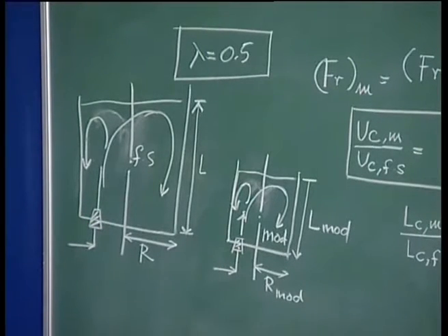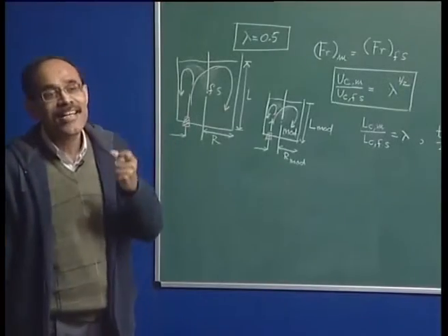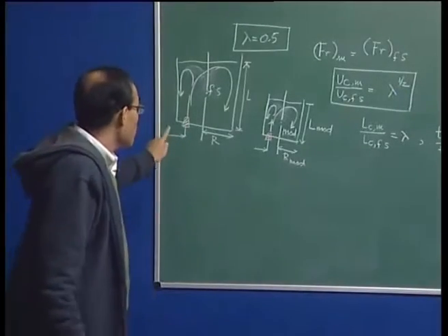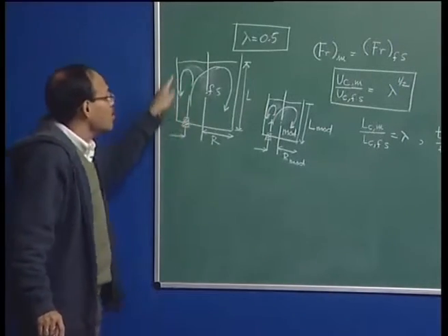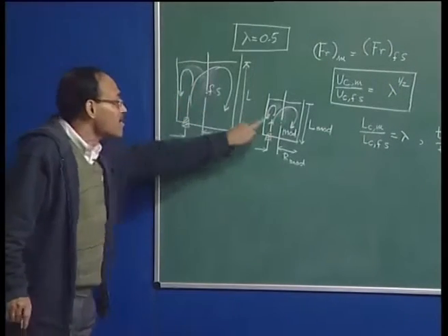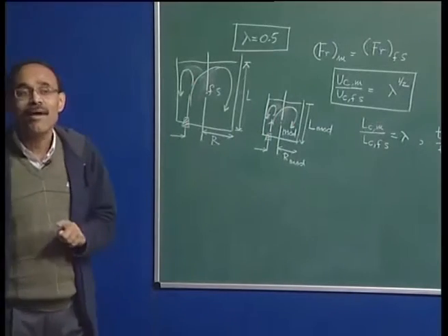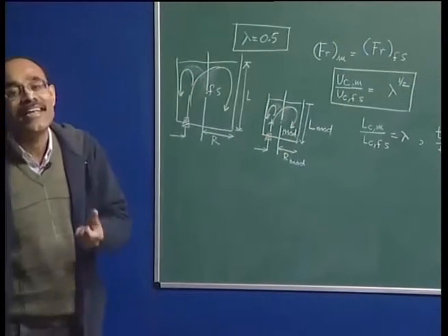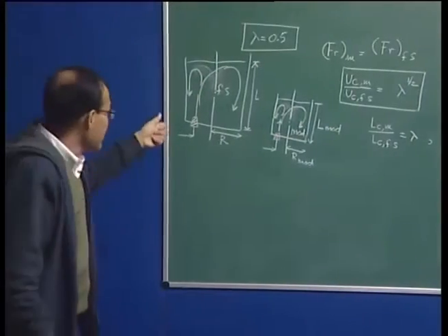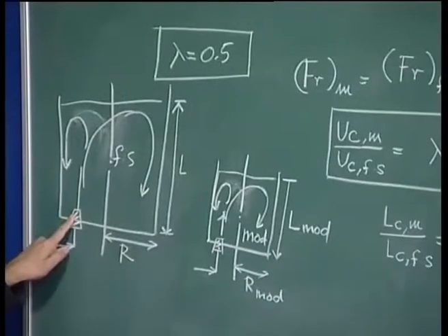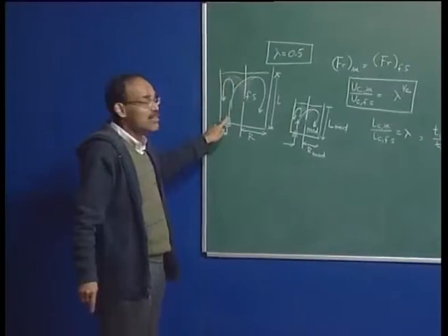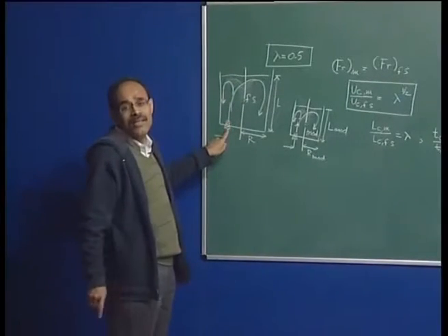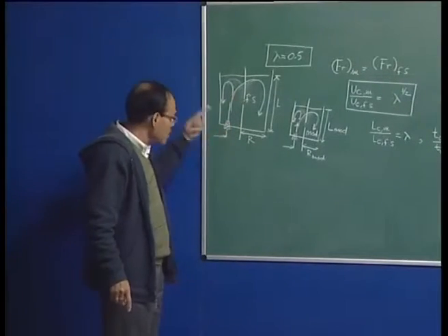Again, remember I said that in the context of gas stirring in ladles, the conditions at the nozzles or the orifice are not critical to the flow recirculation, because these are systems which are driven by potential energy rather than the kinetic energy of the injected gas. The kinetic energy of the injected gas depends on the nozzle diameter, but the potential energy or the buoyancy energy which is supplied by the rising bubbles does not have anything to do with the porous plug or the nozzle.